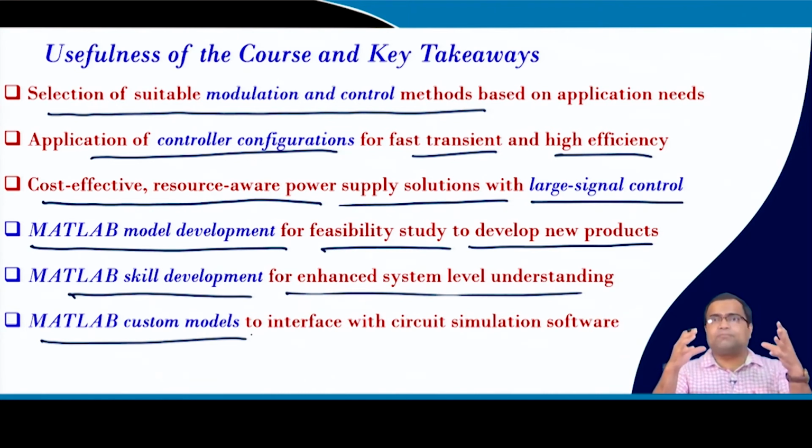Suppose if you use PLECS software with MATLAB, and you can also try MATLAB interface with other tools, whether it is possible to go for Simplis and other professional circuit simulation software, or even you can have one custom model using MATLAB and you can compare that using, let us say, Simplis simulation, or SPICE simulation with the SPICE model of the components. So, you need to compare, because whenever you take a SPICE model from the manufacturer, you may not know the exact model of what is inside.